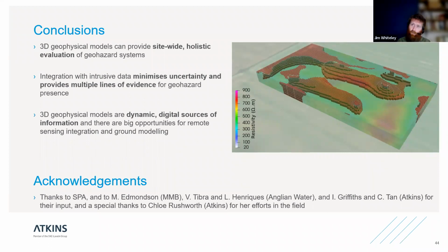And I think geophysics has been used in the past primarily to plan lots of investigations. So where you're going to put your boreholes, what you're going to do next, and quite often it is dropped at that point of the investigation. And I hope today we can show that having geophysics as a 3-dimensional digital deliverable, which can be used in some sort of modeling package and taken forward along with the investigations you get from intrusive approaches, means that you have a product which can go with the lifetime of the project and not just be used as the reconnaissance phase and then dropped. And that's certainly where I'd like to see geophysics going in the next few years.